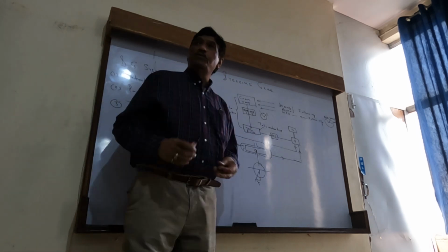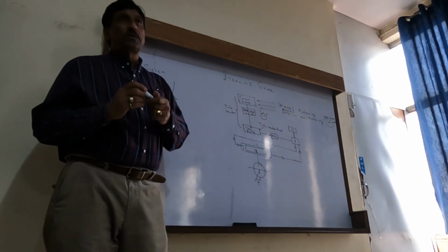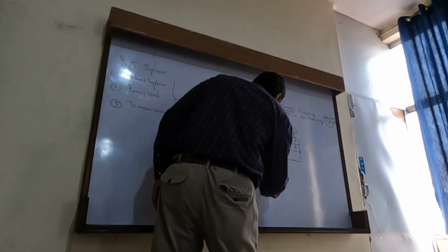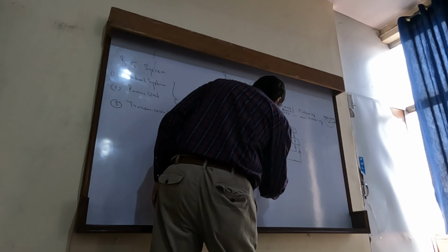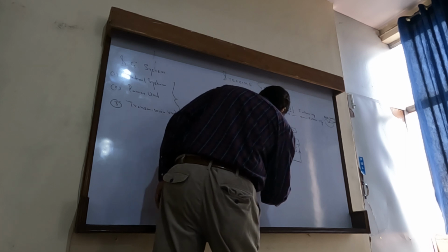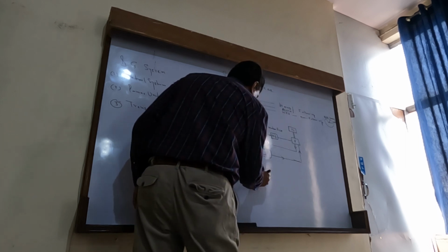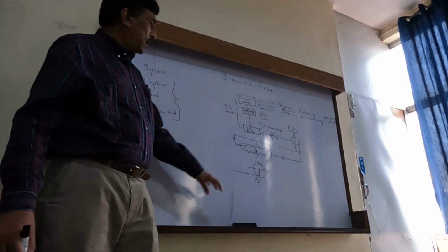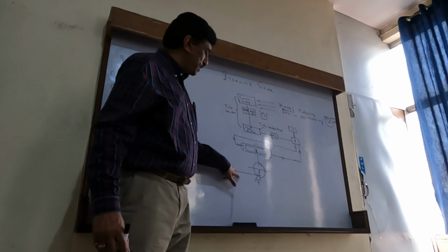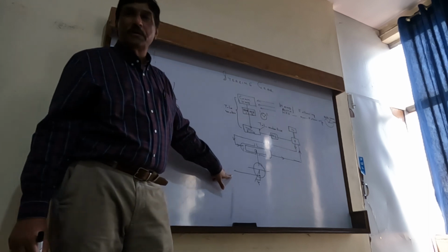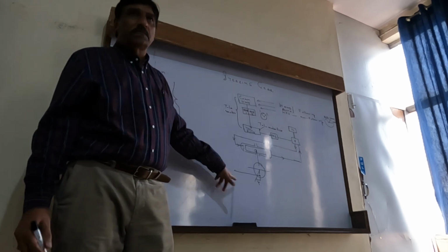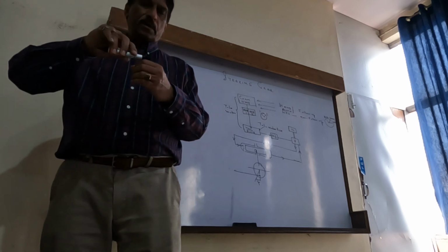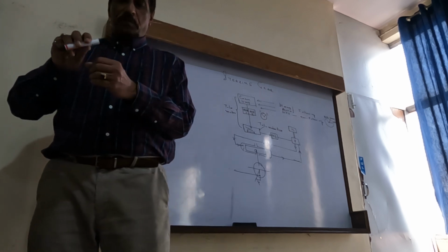Now when the rudder moves, we have what is known as feedback transmitter. Feedback transmitter is connected here on the rudder stock. As the rudder moves, this linkage will move towards left. Yes or no? Here it is fitted like this, it will rotate, it will turn this. If this is a rudder stock,